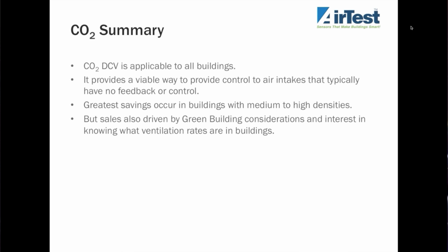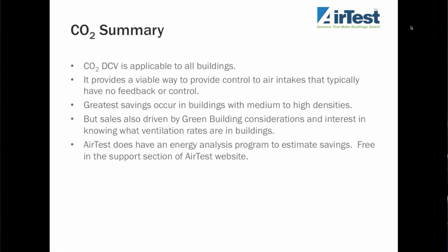So even applications like office buildings are a good candidate for CO2 demand control ventilation because you can actually determine space by space how much fresh air is actually getting to those spaces.